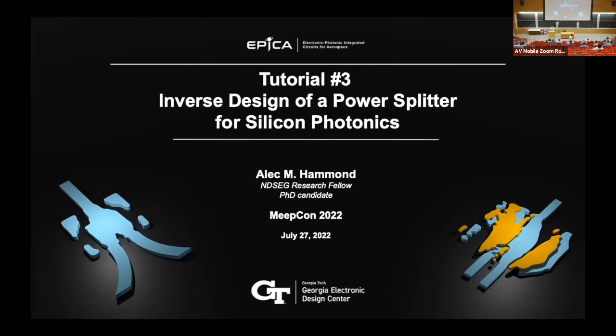So for example, we only care about our figure of merit at 1550. Will the figure of merit function evaluate different values at 1550 if we use one frequency point versus if we use many frequency points in the adjoint solver? I'm mostly thinking about differences due to binning of the fields over the frequency spectrum. Do you have any insight, Stephen?